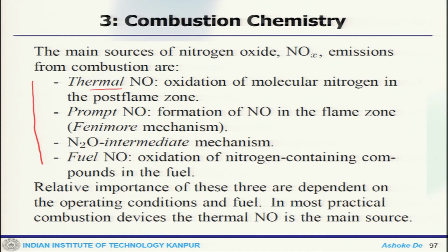Then there is prompt NOx. This is the formation of NO in the flame zone, so that forms within the flame. Then you can also have N2O, which is formed due to an intermediate mechanism, and finally, if your fuel contains some nitrogen, that can also lead to some of this conversion.